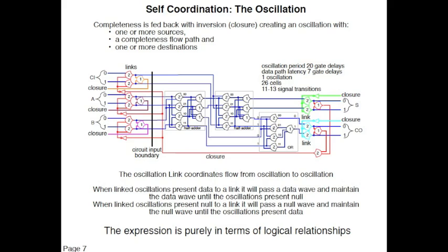So how does all this fit together, and just what is the done signal doing? We'll use a full adder circuit here as our example, composed of a half adder and an OR. It's not a very efficient NCL full adder, but with this circuit everybody will understand how it works, and it has enough structure to support a lot of discussion and a lot of examples. It's a dual rail circuit, 3 dual rail inputs and 2 dual rail outputs. This is the completeness, and this is our done signal.